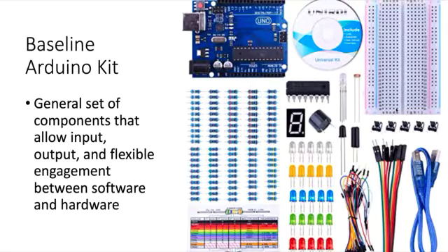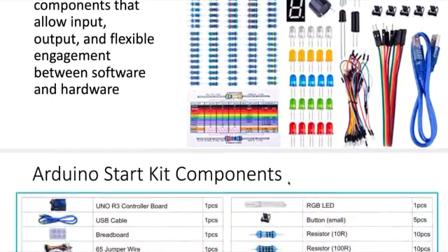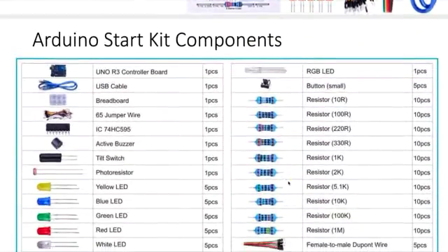So you can be hooking multiple devices without having to pull out a soldering iron and create different types of circuits. And on the edge, all of these up and down from one end to the other are all connected. So that's the first row, those are all connected. And then in the second row, all of these are connected. And the same on the other side. So that just gives you a little bit of an idea of how that works.